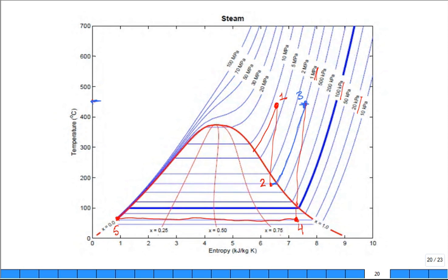So where is that on this diagram? That's probably the hardest one for students to place. Where is state 6? It is so close to 5, it's ridiculous. Right there. But it's on a different blue line. It's on the blue line associated with 8 MPa that comes down and goes over and then goes down.